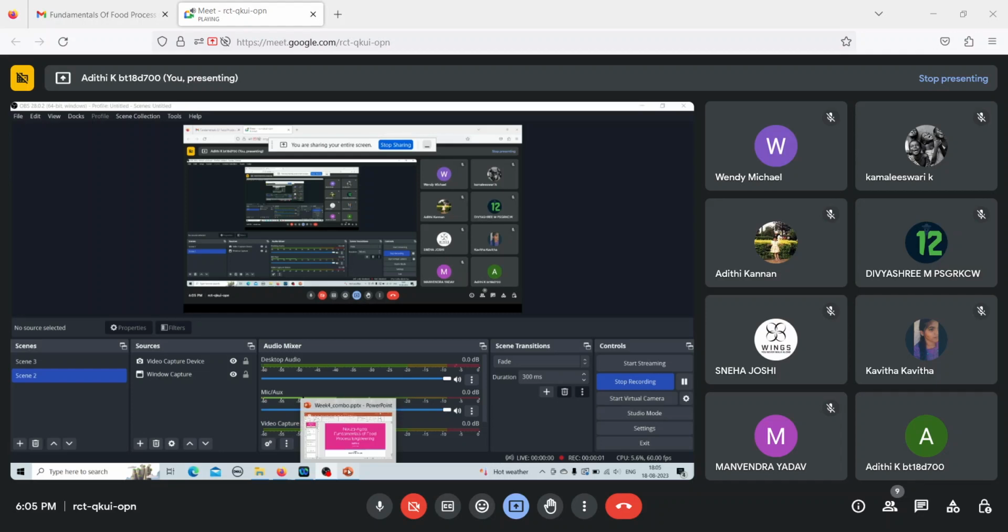So this is one of the equations that you can do. The second equation is you do a mass balance only for the total solids that are present. So the mass of the total solids remains constant also. So F into XF, where XF is the fraction of total solids and F is the total amount of feed that you are sending in, will give me the total amount of solids present in the feed stream. So that is the input, equal to output, which is L into XP. This will give me the total amount of solids present in the product stream.